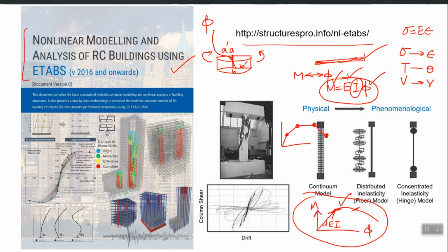So we discussed in the last lecture that capacity we have to provide, and we can provide it at different levels. The fundamental level is the material level, where we make our material nonlinear through the actual stress strain curves and let it manifest at the cross section level, then member level, and then full structure level, right? If we do that, we are actually following what we call the fiber modeling approach, introducing the nonlinearity right at the material level, right?